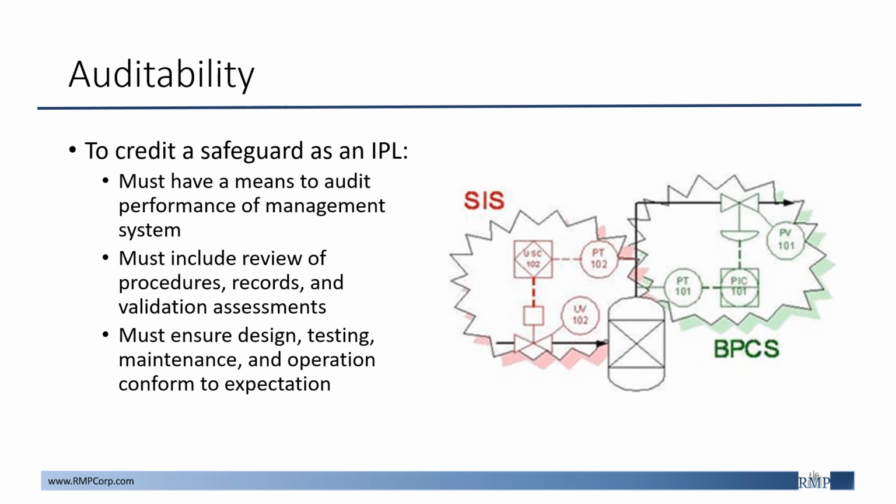So if this is not properly audited, practices may be assumed to be followed, and you may have personnel that may not be properly trained. That would reduce the reliability of your IPL, and you have this false sense of security that your IPL is more robust than it truly is, and that you're crediting this in your LOPA, reducing the overall risk when it's inaccurate to what is existing in your field and in your documentation system.